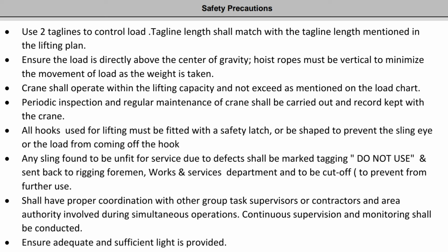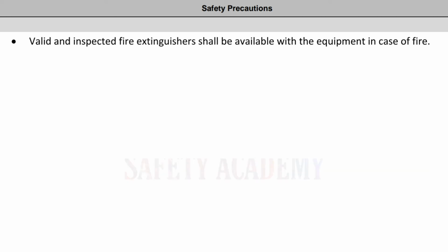Shall have proper coordination with other group task supervisors or contractors and area authority involved during simultaneous operations. Continuous supervision and monitoring shall be conducted. Ensure adequate and sufficient light is provided. Valid and inspected fire extinguishers shall be available with the equipment in case of fire.